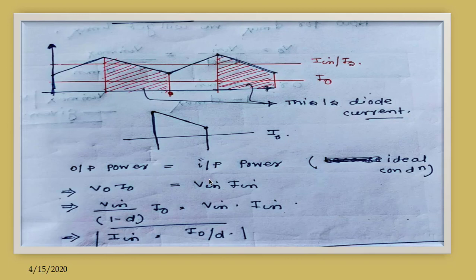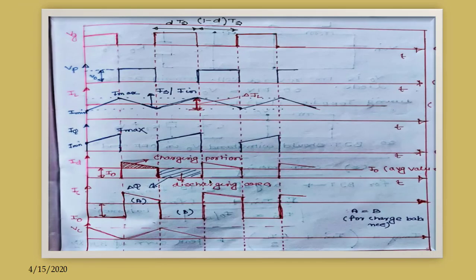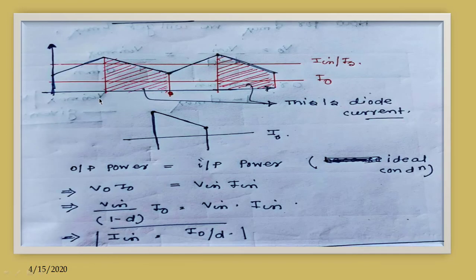Now if we see the waveform of inductor current or the BJT current, so this is my Imax. So this is my diode. In case of diode also it is Imax. This point is Imax and this point is Imin. And this is my delta IL. So what is my Imax? My Imax is the average, that is I in, plus this part, and this total part is del IL, and this part is del IL by 2.